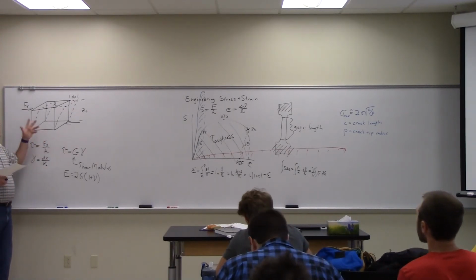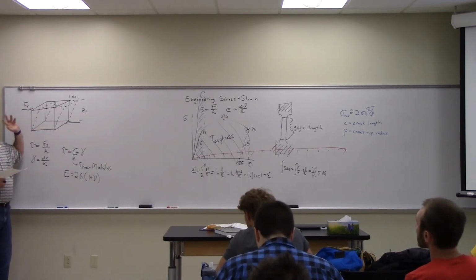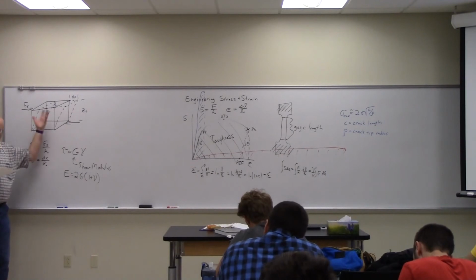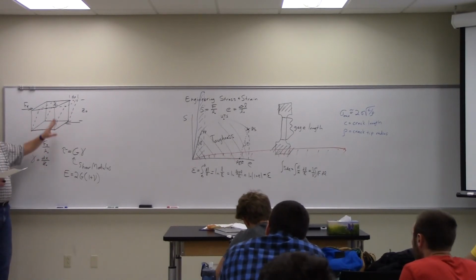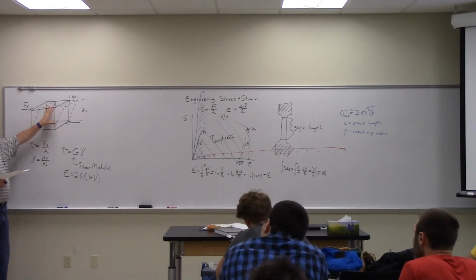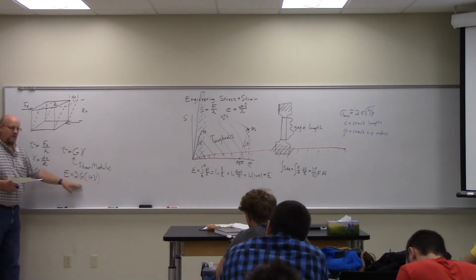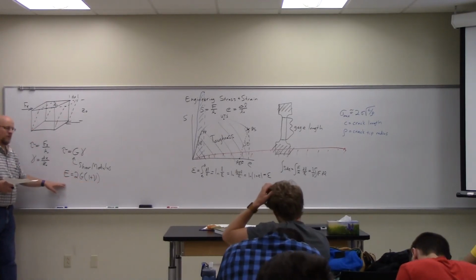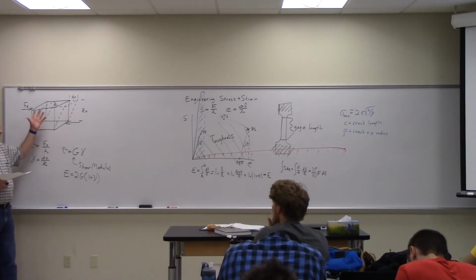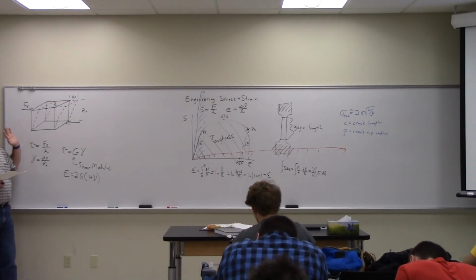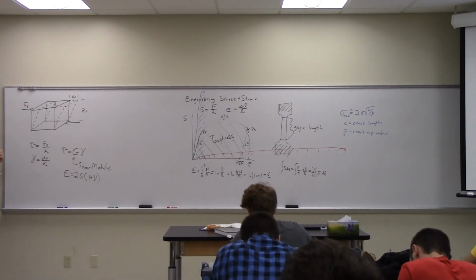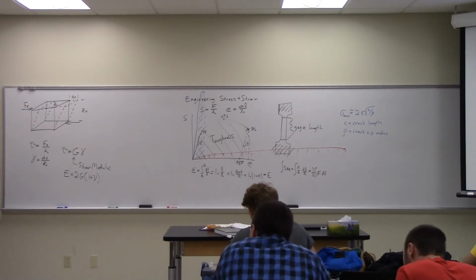So in other words, you don't have something different in the shear direction than you have in the tensile direction. They're correlated. The behavior is measured differently, so the analytical behavior is different because of the way we measure it, but it's still based on the same principles, Young's modulus and Poisson's ratio.